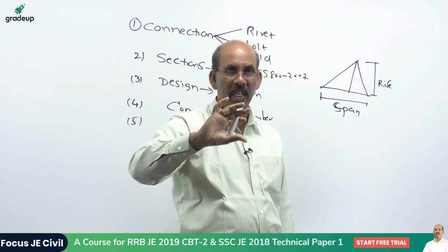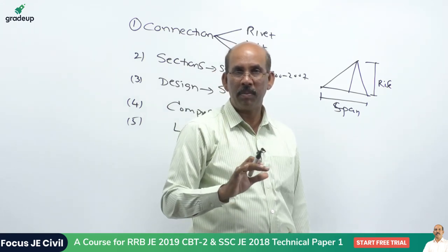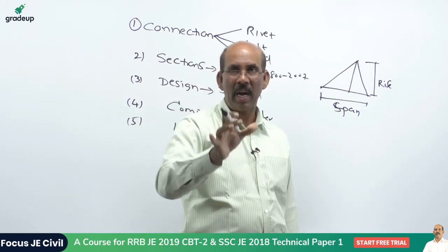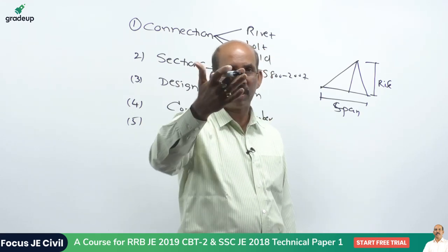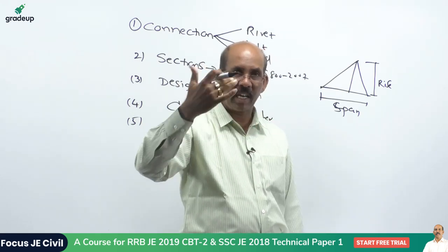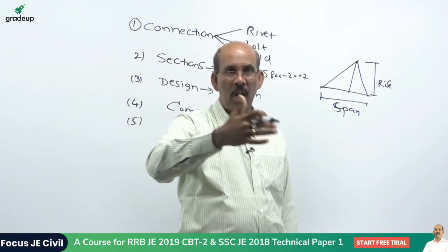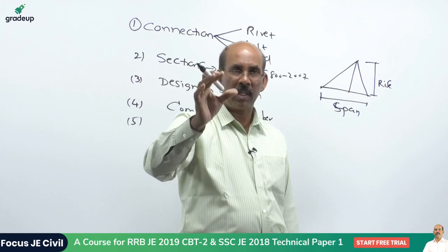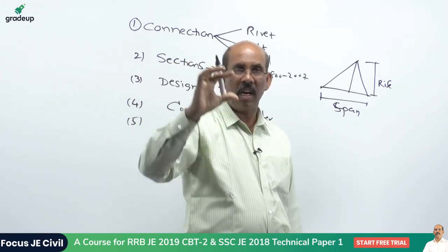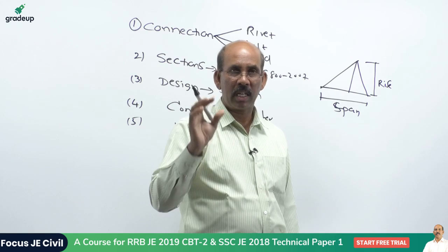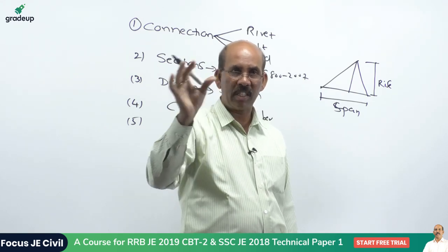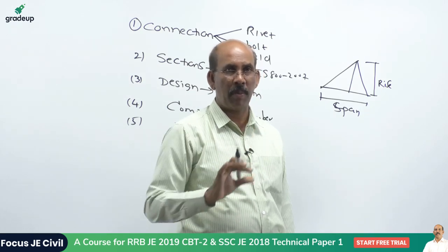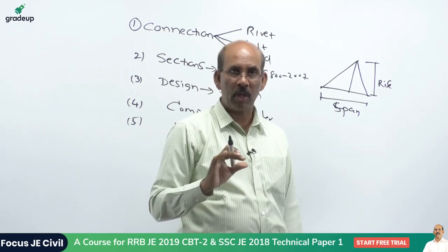The very first thing is we have to calculate this particular angle, and according to that and the span which you have to consider, we select various types of truss like king post truss, queen post truss, howe truss. There are a number of trusses which we have. Surely the pitch, the rise and all these parameters will clearly guide the selection of the truss. We did not cover that till now as per our plan, so surely we will come to your doubt.